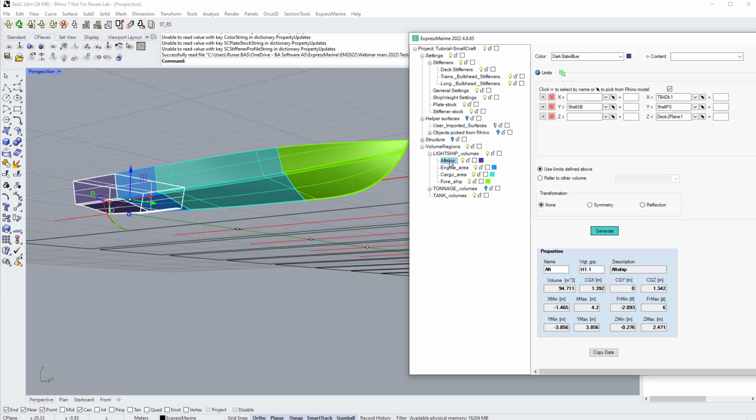So one of the reasons that you want to export this to ShipWeight is at the very early stage, maybe even before you have done any structure like stiffeners and any details. You can just start by bringing in the main bulkheads, watertight bulkheads, and enough to define the ShipWeight volumes, and then you can export this into ShipWeight and start by doing parametric estimation.